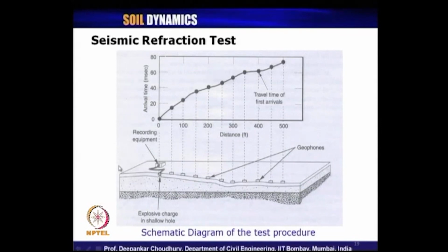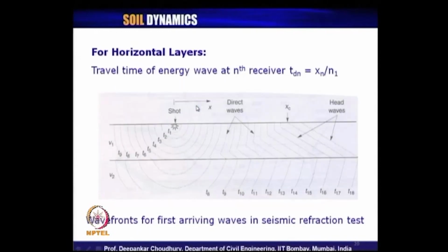So, just to brush up your memories, suppose we have recording equipment here, where the explosive charge at a shallow hole or by using vertical impact or horizontal impact, we are providing the vibration in the soil system, and we are using several receivers which we call geophones at different distances. Then through refraction, we can find out the travel time versus distance curve for the fast arrivals.